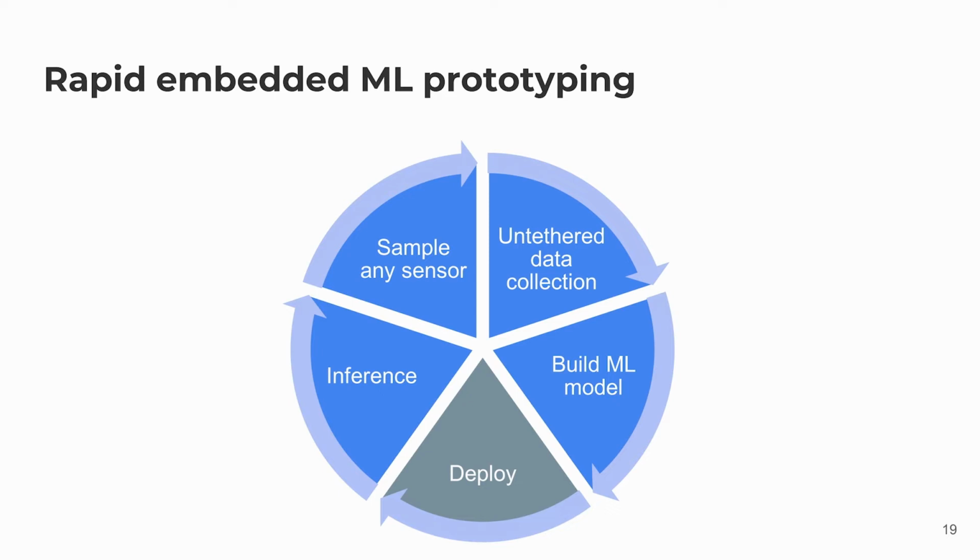Then you can use the app to start inferencing, meaning running the ML model on the Thingy53's nRF5340 SoC, and just reading out the results of the inferencing on the phone's screen. All the processing is being done on the 5340 SoC, but you use the phone's display as an HMI, a human interface, to see what the decisions of the ML are.